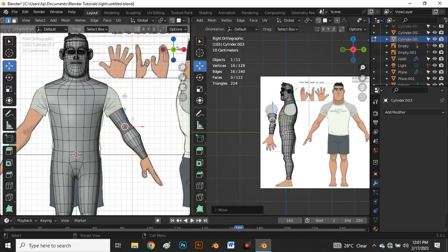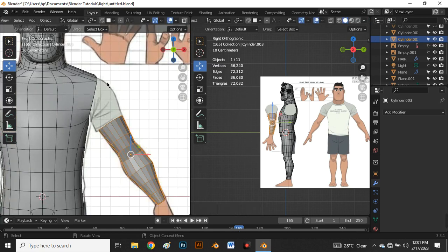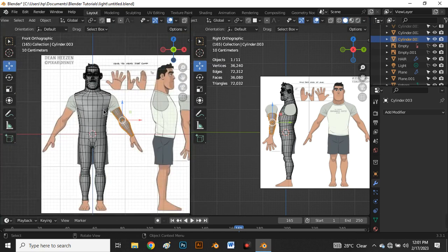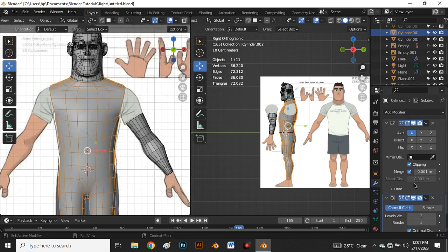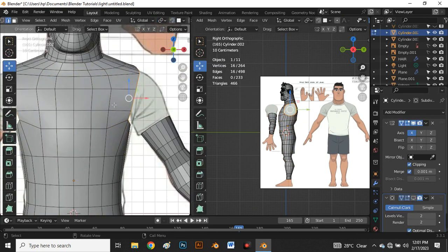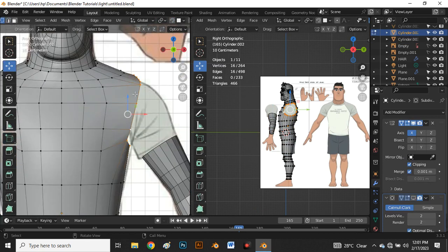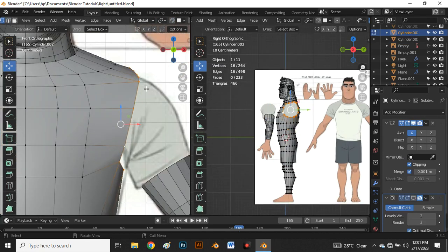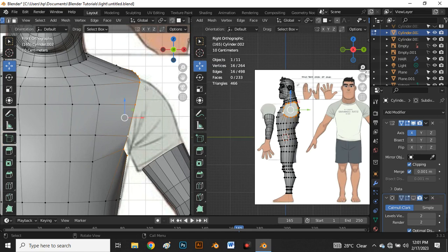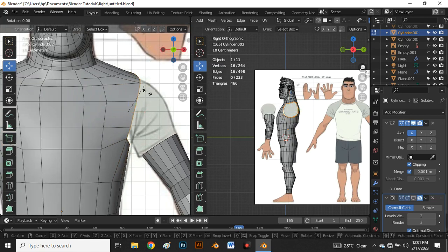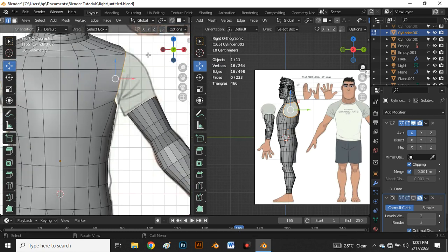So what we'll do next is very simple. We tab for object mode. So select our character body and turn off subdivision surface first, and say Tab for edit mode. Say 1 for vertex selection, and I'm going to rotate this. I say 2 for edge selection, and say R to rotate. So I want to rotate this loop here.